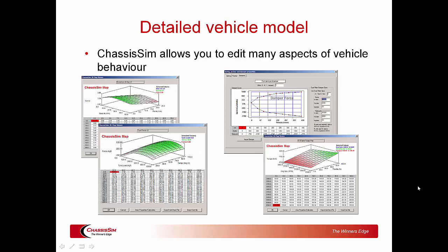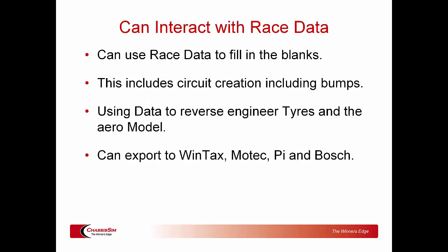Now, at the core of ChassisSim Elite, ladies and gentlemen, is a highly detailed multi-body dynamic vehicle dynamics model. So here's just a quick sample of what you can do with ChassisSim Elite. You can drill down to a highly detailed aero model and a highly detailed thermomechanical tire model. You've also got the ability to specify nonlinear damper models as well as 3D engine torque maps. But honestly, with things such as the electric powertrain module and our curves module, what you're seeing there literally is just scratching the surface.